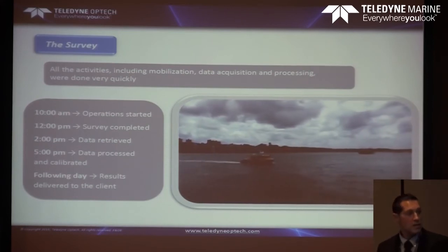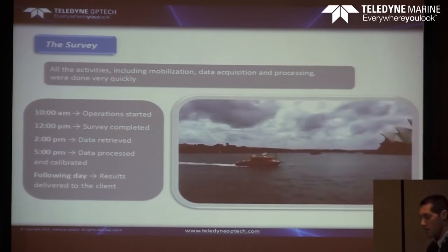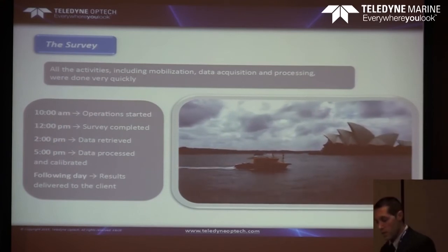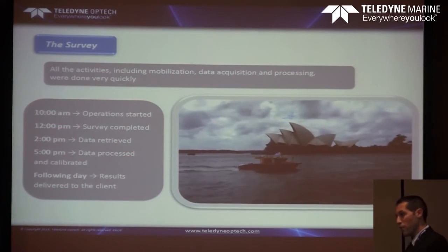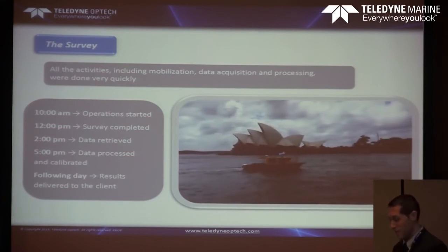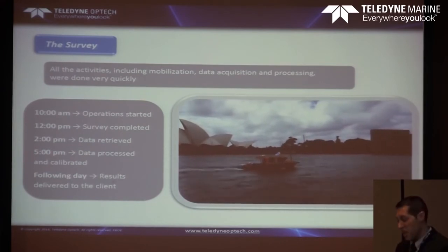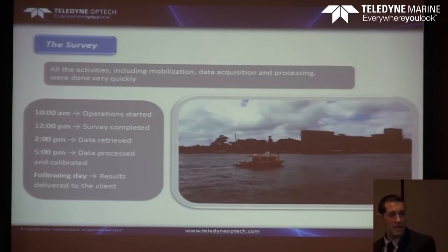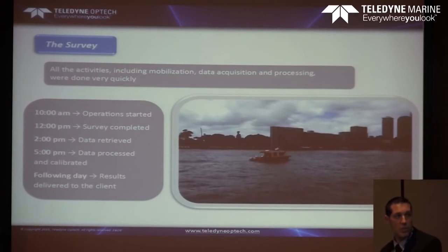Then, after 2 hours, we retrieved the data set from the hard disk of the computer inside. It's a lot of data, of course. 2 hours of survey from both bathymetry and laser scanner is a lot of data that you collect. You do the processing. It took 3 hours, and at 5 o'clock everything was already calibrated. And we actually delivered the data set the day after to the Port Authority.